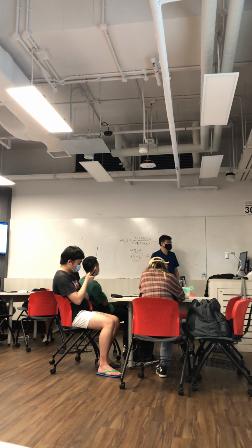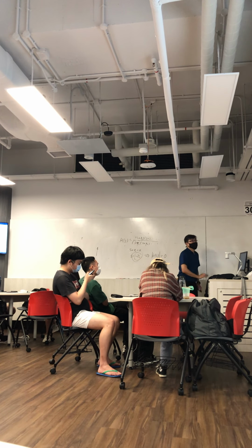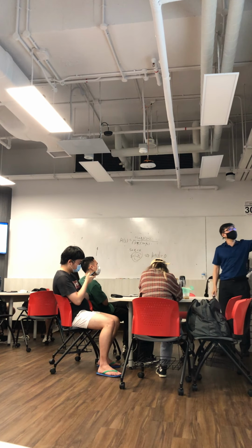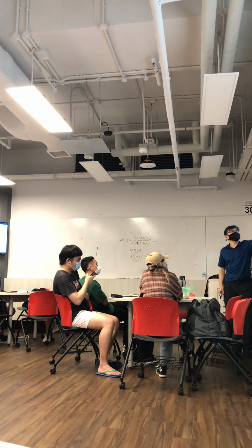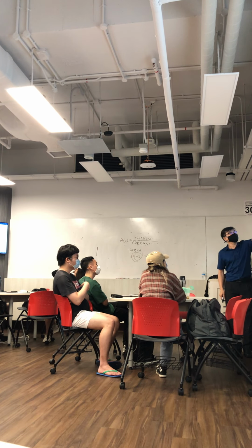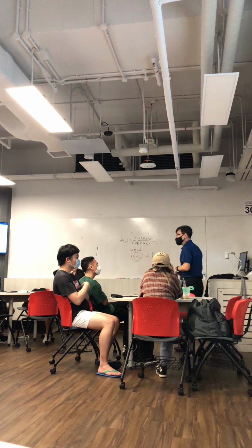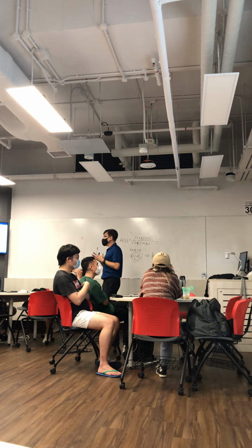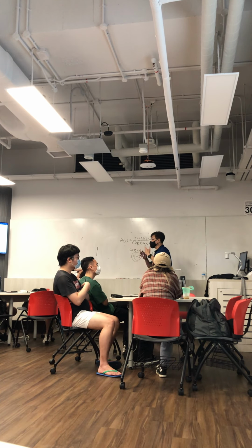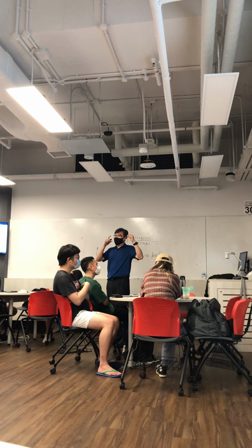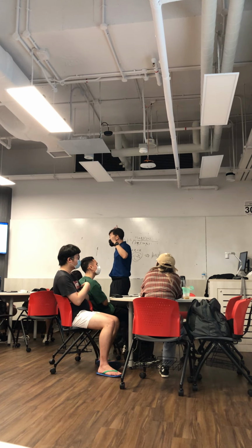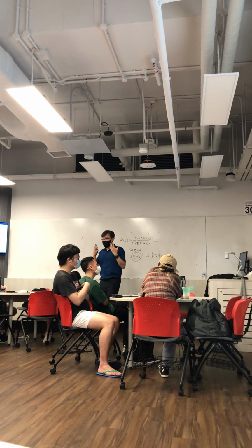Okay? So now if I show you this, can you tell me where the zeros are? The zeros are at minus 1 and minus 2. The poles of the other transfer function are at these three crosses here: minus 3, minus 1 plus j, and minus 1 minus j. You can see that the poles always occur in conjugate form. If it's real, then you will just have the real one. If it's complex, then you always have two in conjugate form. That's what I'm trying to say.